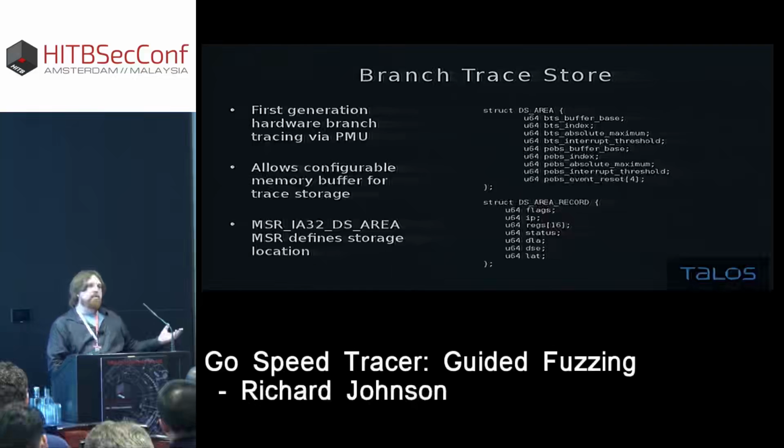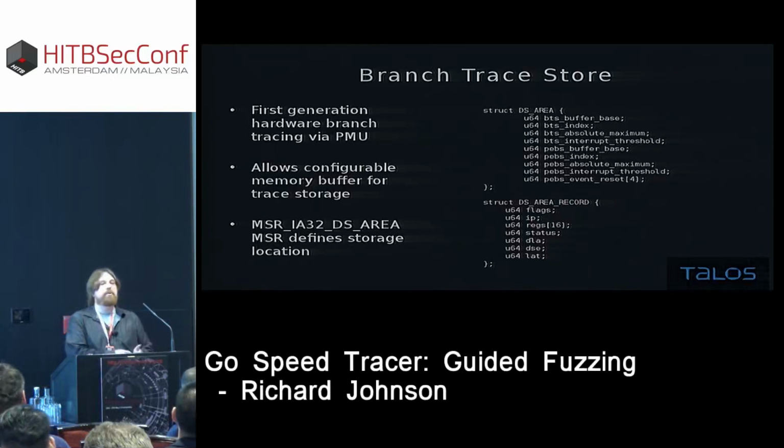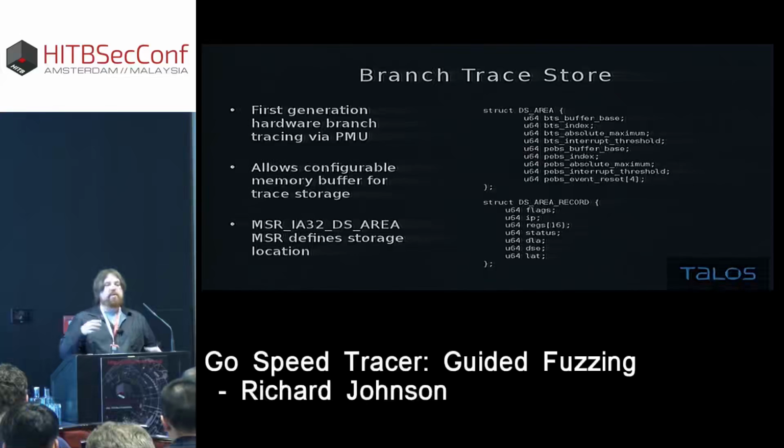So basically, when you program a CPU and you're doing this low-level programming, there's a whole series of instructions not normally accessible to you in user mode for standard application programming. And these are the model-specific registers, or MSRs. What they allow you to do is put the CPU into special operating modes, including some of these tracing functions. It's also how you would do things like set up SMM memory, or enable anything in the PMU, anything that's on core that is not part of your typical operation of the CPU. Those are configured through MSR registers.